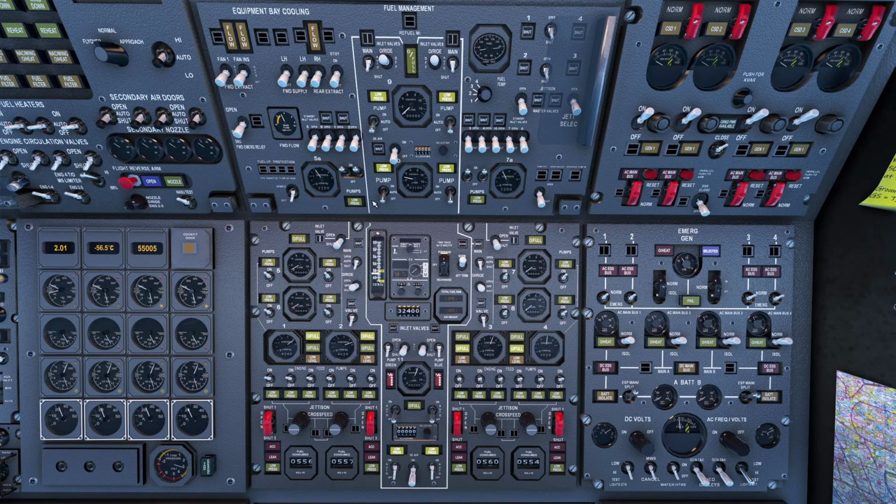Transfer process is pumps are always on, so you don't need to open the pumps, you just need to open the inlet valves of tanks 5 and 7, and our CG is gonna go back as this fuel flows, so we have to open pumps tank 9, 10 and the inlet valves of tank 11, and hopefully get them more or less in balance, or otherwise stop the pumps so we can catch up, because the fuel flow is quite a bit more in this direction here than from the front to the back.